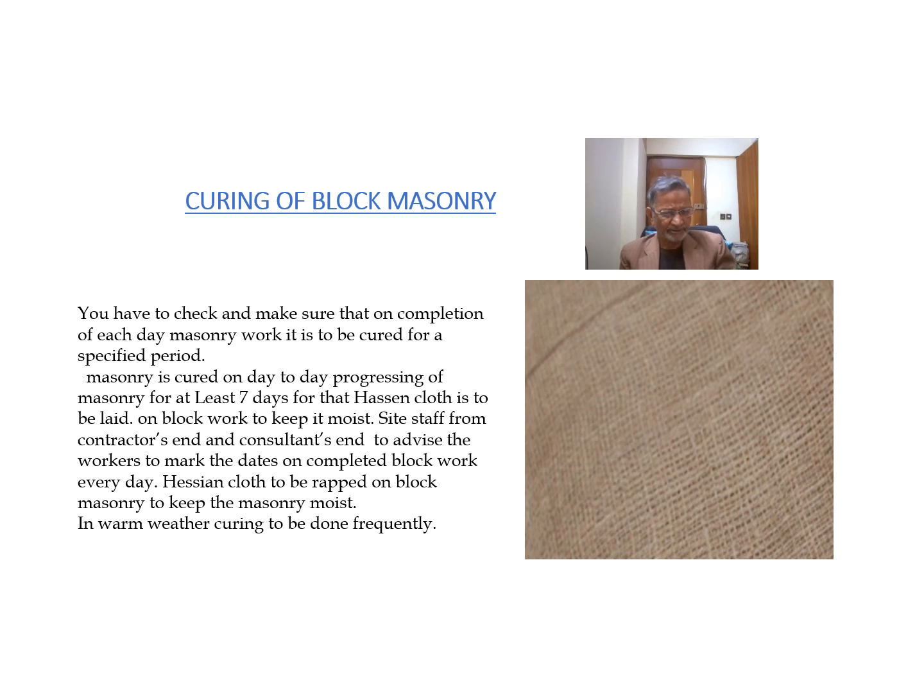So the site staff from the contractor end should instruct the mason, or himself write the date of the masonry completed every day, so that the curing period is completed for each and every section and every part of the masonry. In all the rooms, different timings are given for the masonry. So masonry should be cured for at least 7 days, so that it can get proper strength of the block masonry. Thank you very much.